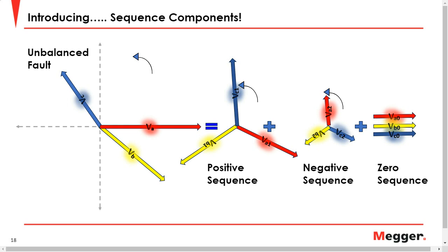If they're produced on the Y side and there is a neutral, they will circulate through that neutral. The transformer will provide ampere balance, so if the triple harmonics are on the Y side, they will be present inside of the delta. You have the ampere balance for the transformer winding, but they won't show on the line right outside of the delta. So that comment, whoever made it, is a very valid and very good comment.